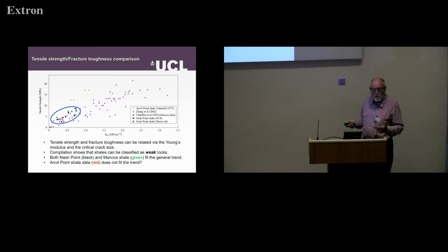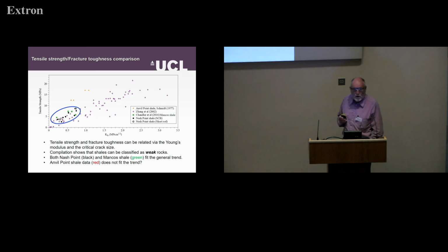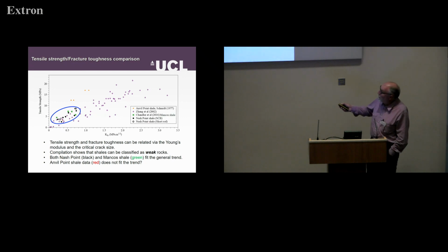There's very little data on shale, and the only previous study we could find where both things have been measured is some measurements on Anvil Point shale back in the 1970s, and that does not fit the trend, and we think that's because they used a rather dubious method for measuring fracture toughness, which is no longer considered an appropriate way to do that. So it doesn't fit the trend. It sits up here. The fracture toughnesses were too low.